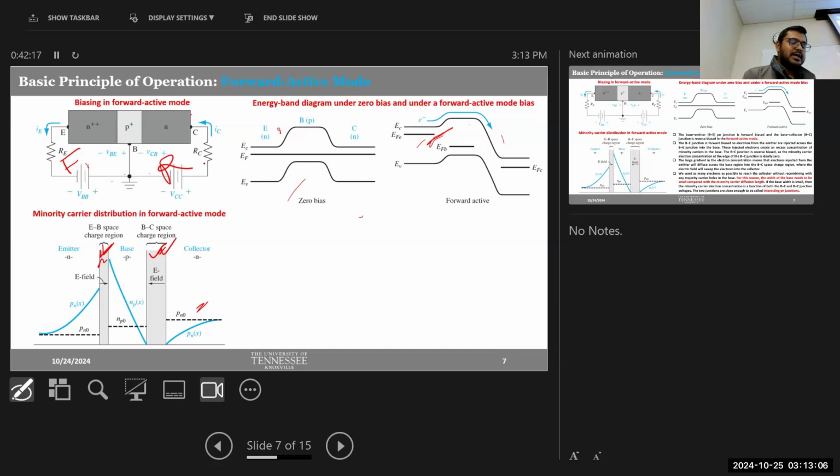Okay. Now, as I mentioned, we will mostly focus on the minority carrier. If we look at the emitter side, which is an N-type material, here our minority carrier is the hole, right? And we know this notation, I guess, p_n0. What does this notation mean? Do you know this? You should have seen this in the PN junction lecture, I guess. Here p means the number of holes, or doping concentration of holes. n means the region, so the number of holes in the N region. 0 means the equilibrium condition, thermal equilibrium.